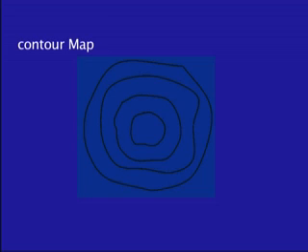all the various points or the various locations, these could be some landmarks, it could be the top of a building, or it could be the bottom of a building, or it could be the top of a tree or the bottom of a tree, and so on and so forth, the various landmarks, or it could be just the surface of the earth or soil. These points with the same altitude or height are joined by a curve, and these are called contours. And then you have a set of such curves for various values of the height, and such a map is known as a contour map.